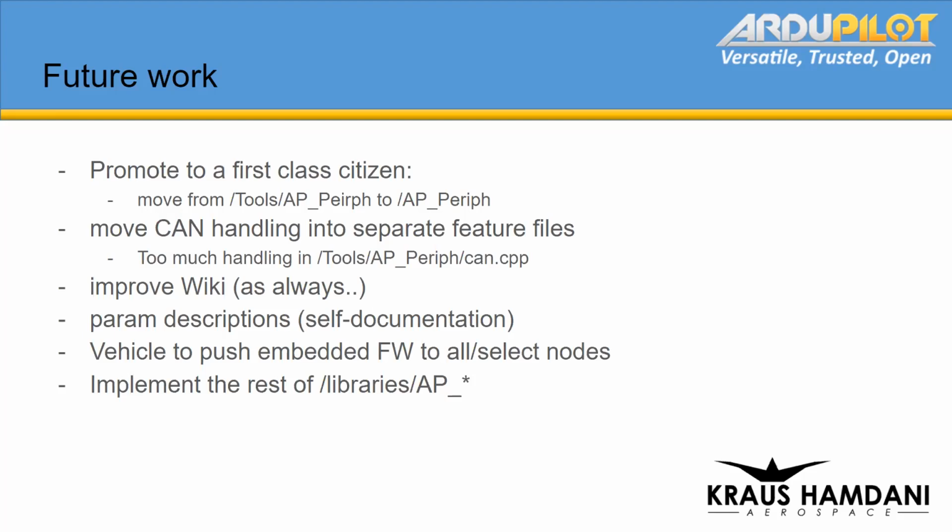Also, there's a whole lot of code being handled in the can.cpp file. So we should probably try to abstract those out a little bit more. A lot of the features are wrapped around #if defines to enable them, so the file size is real small. But a lot of it's kind of just thrown into this can.cpp. It's still commented or if defined out, but a lot of the handling is kind of happening in one place. So we might want to rearrange this a bit. It works right now, but it's kind of getting unwieldy as we're adding this onslaught of features.